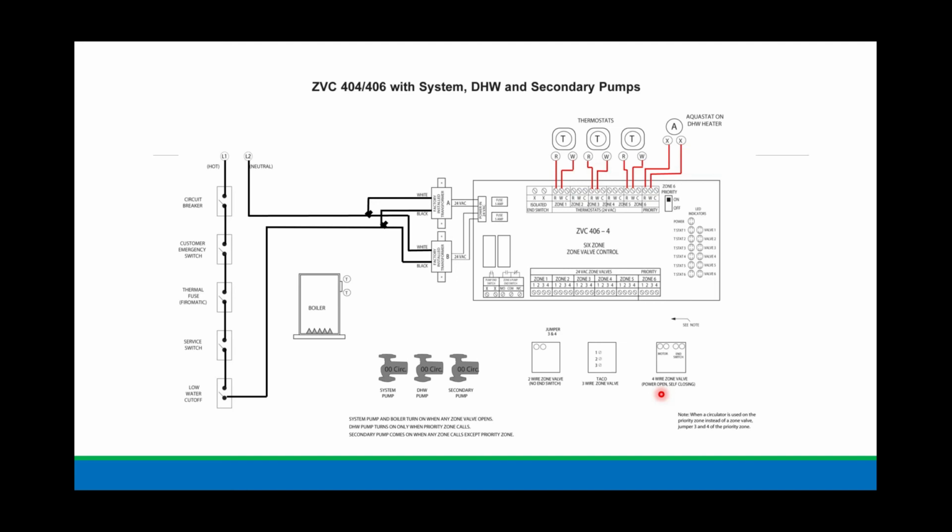Now, this is really cool. I give you 4 terminals. So whether you have a 2-wire with no end switch, the Tekmore 3-terminal 571, or whether you have anybody's 4-wire zone valve, and I'm going to be talking here about Zone Sentry, we can wire them all up on the same panel at the same time.